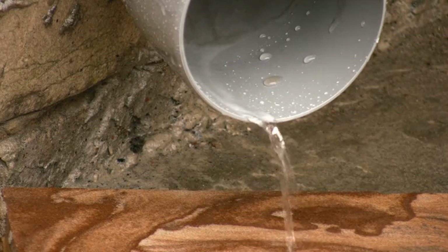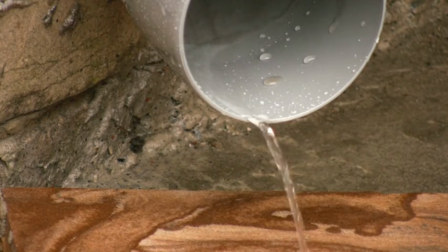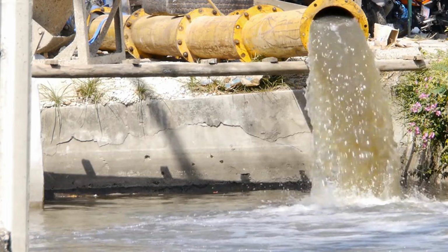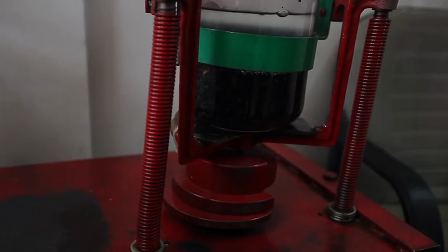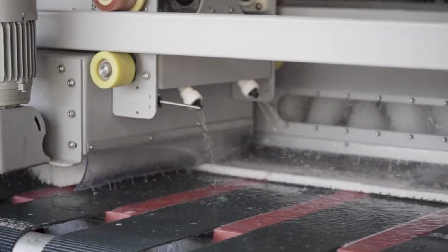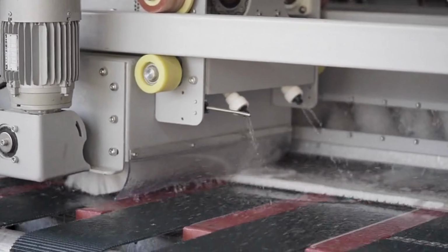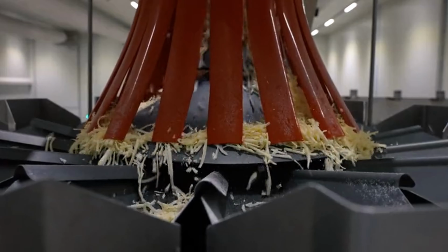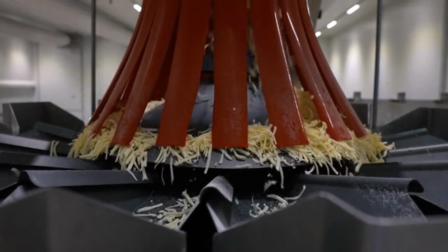B. Advanced water removal. Water is removed in 4 stages. Gravity drainage achieves 20% solids. Vacuum suction removes another 10% of water. The pressing section further reduces moisture to 50%. Infrared and steam drying brings moisture to 5 to 8%.